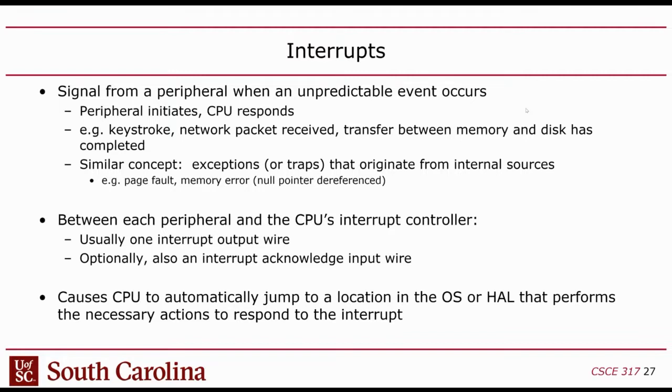It's impossible. The only way for that to happen is for the peripheral to get the CPU's attention, and once the peripheral has its attention, the CPU would then query the peripheral through programmed I/O. So this is a way to get the CPU to initiate an interrogation through programmed I/O, a way the peripheral can get the CPU to interrogate it, to find out what's going on.